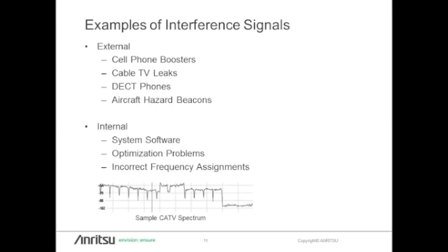And one example, which I'll mention in a slide or two, is cable TV, CATV systems, and there's a little diagram. These are generally about 6 megahertz wide, and in North America, or really all over the world, they're operating in a multitude of frequencies, anywhere from a few hundred megahertz, all the way up to, I've seen up to 1 gigahertz. So these systems are very prevalent in leakers, and if you look at a pattern on a spectrum analyzer, and you see something like the bottom of this chart, you have a pretty good idea that you're looking for cable TV leakage.